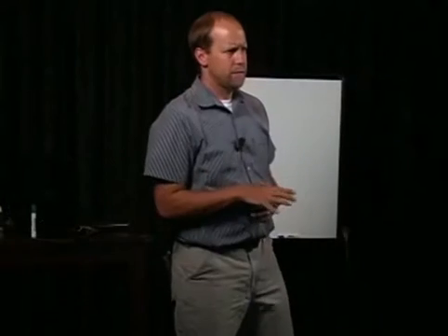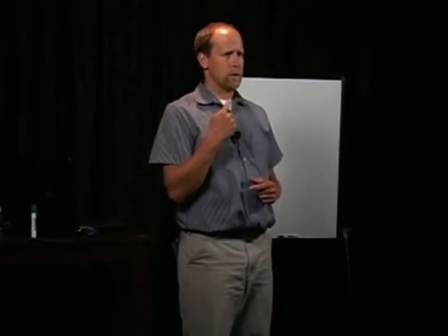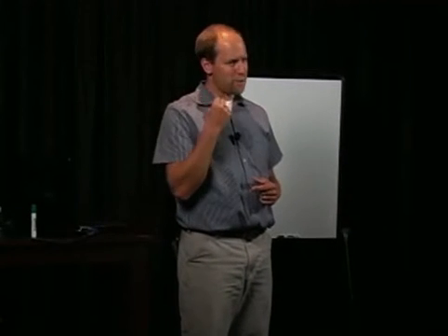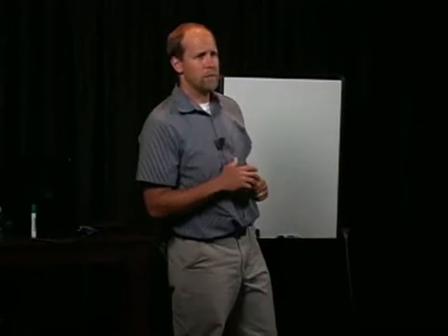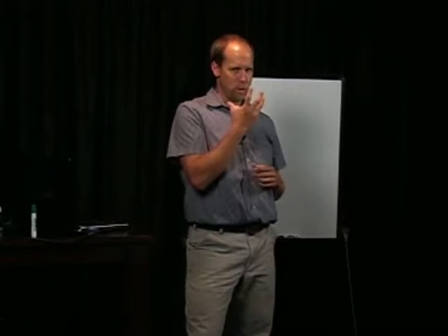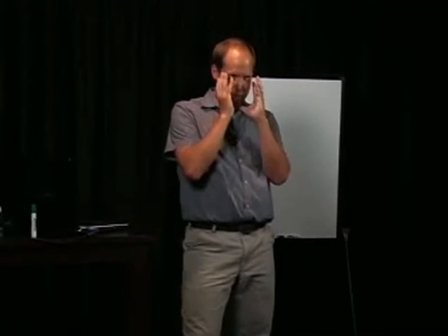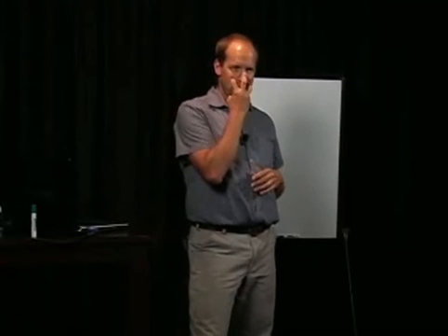Eye protection should be worn during an inspection where mold is visually evident, or at least it should be available. Airborne mold spores, particles, and materials can enter the body through the eye. Goggles, safety glasses, and eye shields are readily available. Safety glasses or goggles that have open holes on the sides are really not efficient, not acceptable. A full face respirator has eye protection. A lower face respirator doesn't.